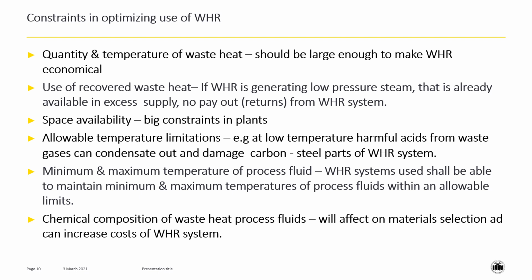Allowable temperature limitations are important because many a times at low temperatures harmful acids will condense out from the waste gases and they may damage carbon steel parts of the waste heat recovery system. So there are restrictions in reducing temperatures of waste gases in many cases.